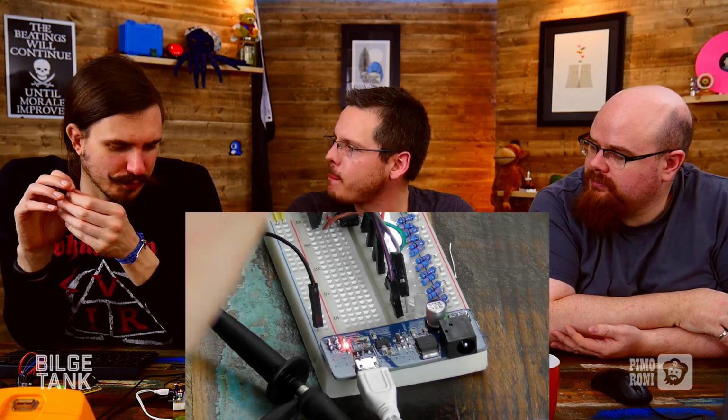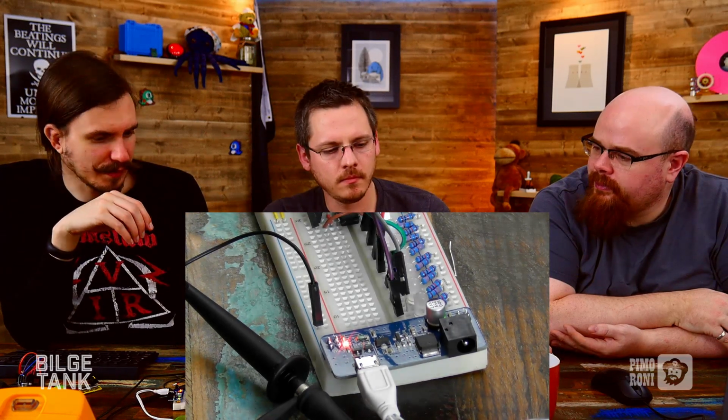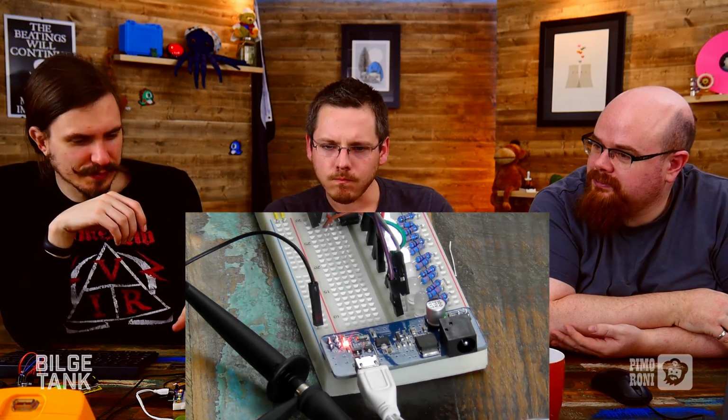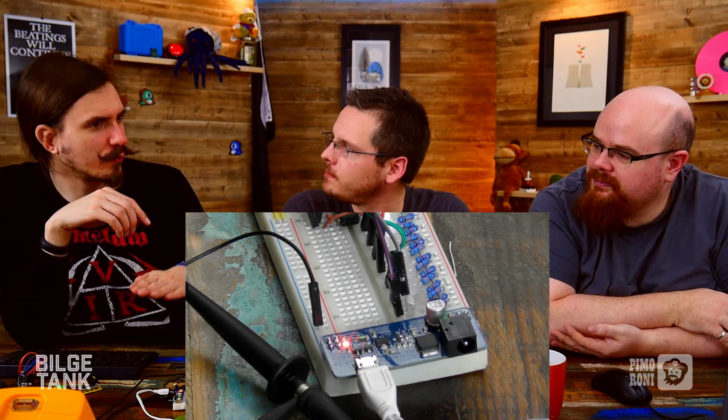The other way that's not used very often that I read about is where you have a decade counter or an 8-bit counter, and you have a resistor ladder coming off that counter with various different resistance values. You run that counter and it produces all the voltage ranges possible between your ground voltage and your maximum measurement voltage. Then you take your input voltage and you keep comparing it, and at the point when they're equal, you say, aha! The value that's then in your counter is the correct value, your ADC value, which means you've got to constantly be running this counter round and round in order to do the comparison. But I suppose that's not necessarily...